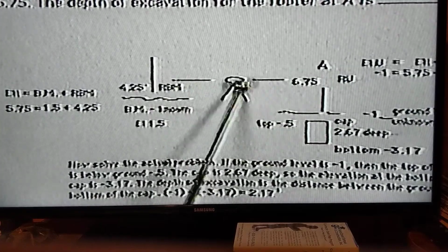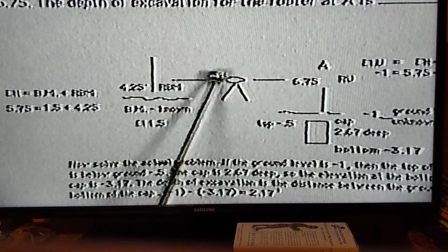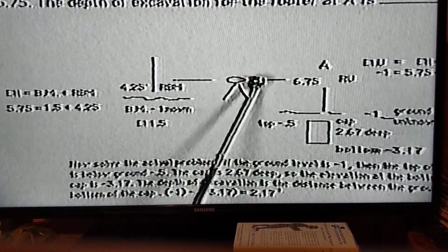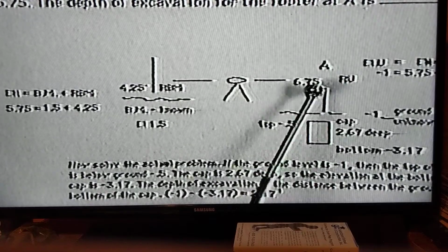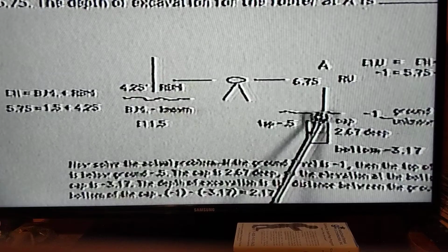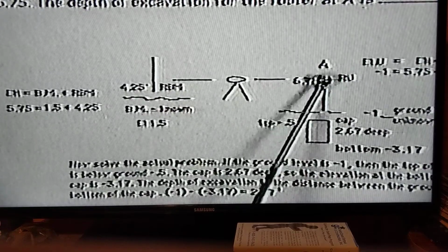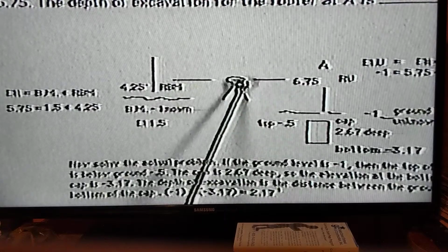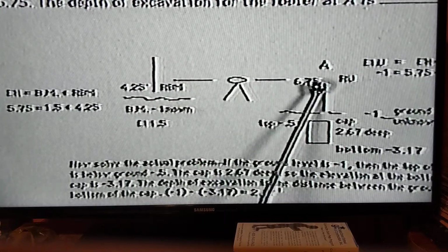what elevation this line of sight is at, then when you look from the point of view of this line of sight at a location where you have an unknown elevation, and if you were to place a rod in that location, and this rod had numbers on it, you would be looking through here and you would be seeing a number.